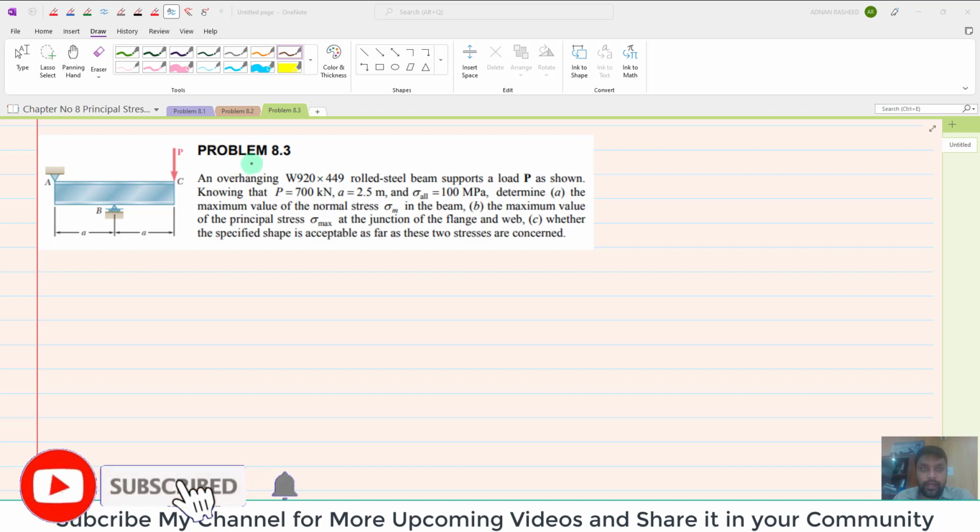Welcome back. Problem 8.3. The statement of the problem is: an overhanging W920 by 449 rolled steel beam supports a load P as shown. So you can see this is an overhanging beam and it supports load P at point C. P is equal to 700 kilonewton, this distance A is 2.5 meter, and the allowable stress is 100 megapascal. So you have to determine the maximum value of normal stress sigma m in the beam. Part B is the maximum value of principal stresses at the junction of flange and web, and see whether the specified shape is acceptable or not.